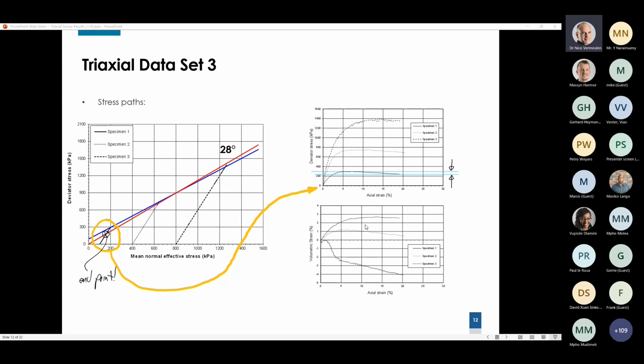Some of these samples are flushed prior to saturation for B values, then saturation, then consolidation, then shear, then dismantling, and then getting the final void ratio. So on both ends, you've got a reasonably accurate number, but it's often very difficult to track the changes throughout the whole process. And that creates complications and difficulties of its own, not necessarily with the shear strength parameters, but with some of the other parameters. But that's a talk for a whole other night.